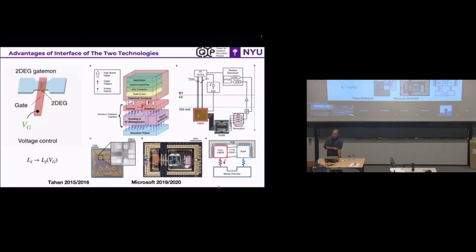From the physics point of view or the engineering point of view, when I have this device that has aluminum and some indium arsenide or a semiconductor in the middle, with aluminum oxide it was just tunneling, right? But now I have a transistor where the source and drain are superconducting, and on top of that, I can put a gate that controls the number of electrons in my semiconductor. So I can get supercurrent out of this device, but by changing the gate voltage, I can deplete my electrons so that the supercurrent drops and almost vanishes. So I can create a gate-tunable supercurrent in some sense, right? So this is my Josephson field effect transistor.